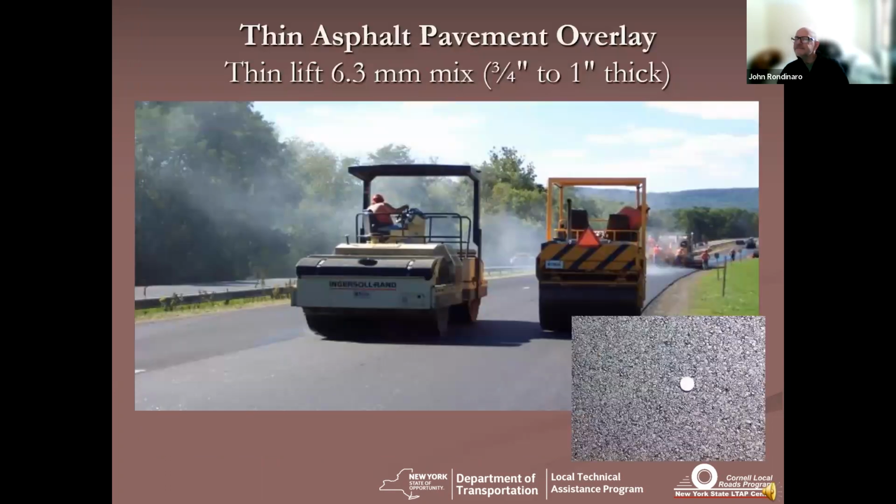We have another question. How do you achieve proper compaction and rut filling? All right, in terms of microsurfacing, you don't do compaction. If you were using it, you'd run your rut fill in, it would be struck off within the rut, and then you'd come back in sometimes with a scratch course, sometimes with a scratch course combined with a surface course, and sometimes just with a surface course.